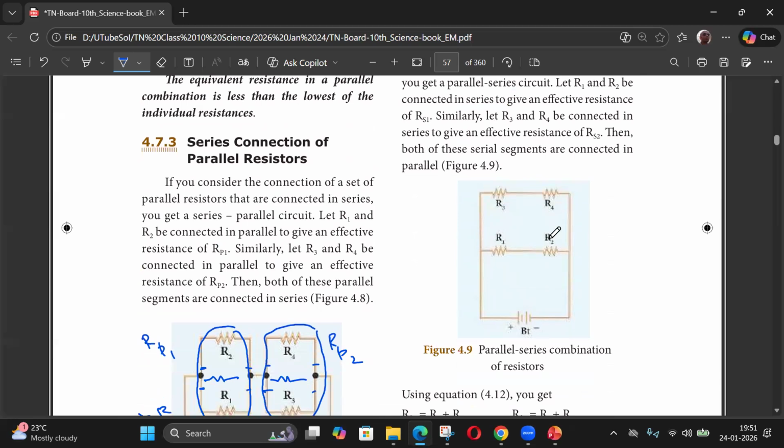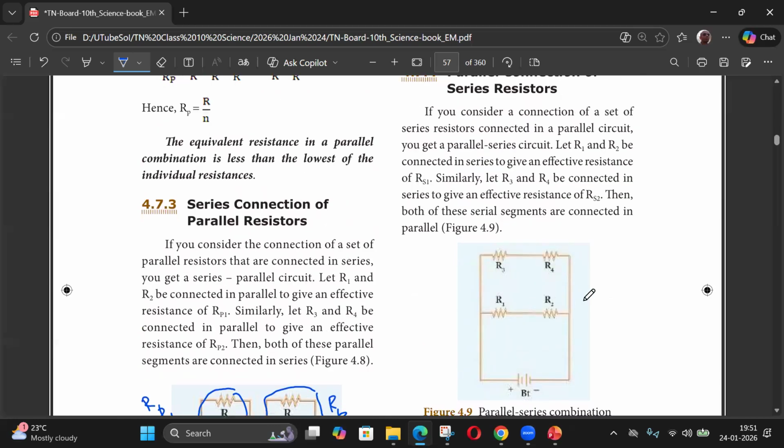Here it is a similar one. So how do you reduce it? Same, R3 and R1 are parallel? No. See, the voltage here and the voltage here are the same, but this voltage and this voltage need not be the same. Then these are series-parallels. First, you have to combine these two. Do it step by step. These two are in what? Series or parallel?